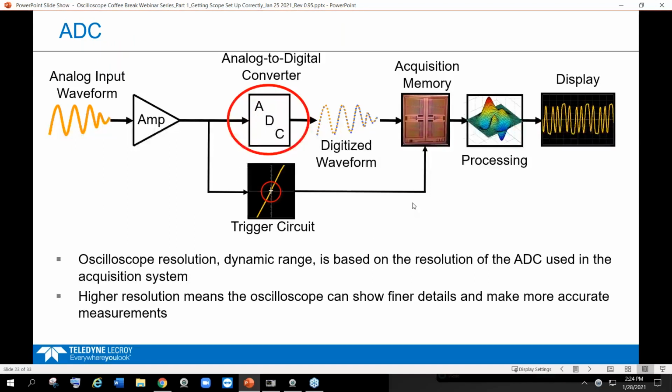Of course, there is our ADC, and all oscilloscopes have hardware ADCs. There are many times they're supported with post-processing to get higher effective number of bits, but we are basically going to use that ADC with the sample and hold, and using the number of ADC bits and quantization levels, we're going to create and store all the voltage values in this case and convert them to a number.